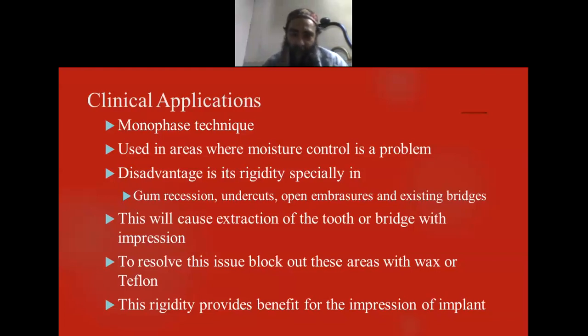You can imagine how stronger its grip is and how difficult to remove it from an undercut area. To resolve this issue, block out these areas with wax or Teflon. So block out means cover up, to block the undercut areas with wax or Teflon, the same Teflon which we use in our household environment